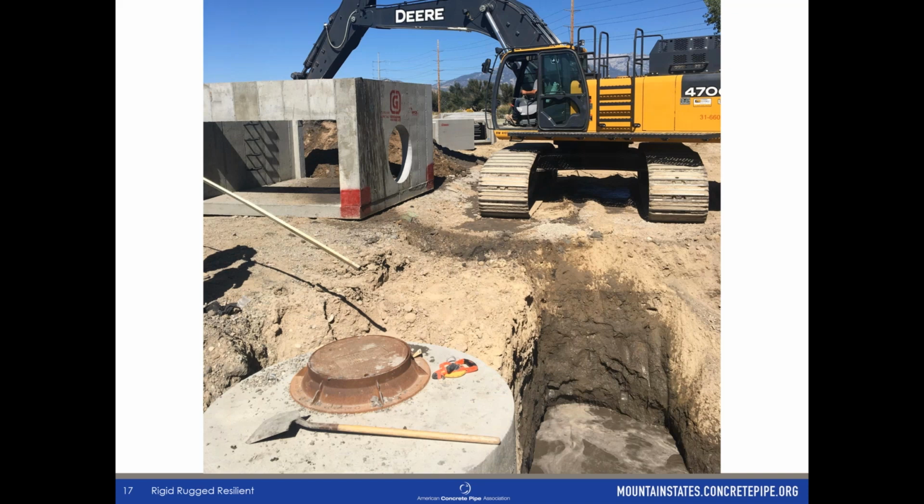So concrete pipe and box culvert was a very good option and alternative for this project, because concrete pipe has a tendency to be able to withstand flotation much better than some of the flexible products. And so this project had over 13,000 feet of reinforced concrete pipe in it, ranging from 15 inches up to 36 inches.